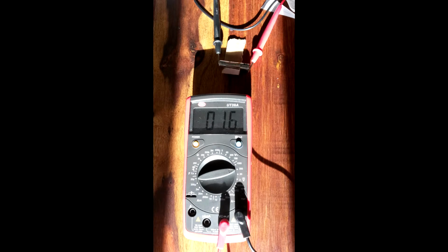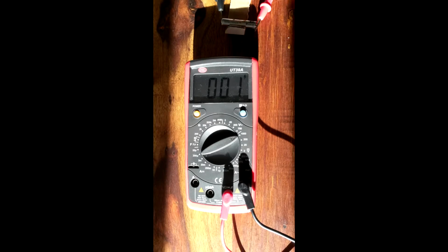And here we have the same multimeter set to 200 volts. The reading is 1.6. Now, obviously, as we get higher up the range, we're going to get fewer decimal places for the volt reading. And finally, we have the voltmeter set to 1000 volts. Now, the reading is 001. This usually happens when your range is too large for the object that you're trying to read the voltage of.